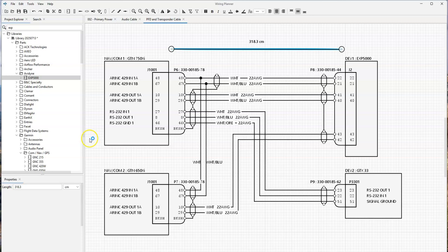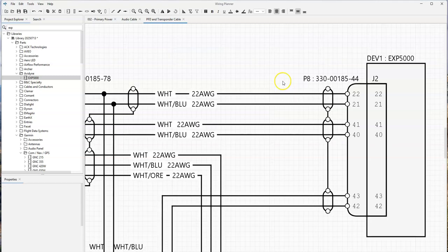And if you select this measurement line, here in the Properties panel, you can see the length and you can change this to whatever length you need. So 24 inches, for example, you can change the units. You can also place the measurement tool at an angle if you need to annotate something at an angle. And when you place the measurement line, you can use the control key to constrain it to 15-degree angle increments.